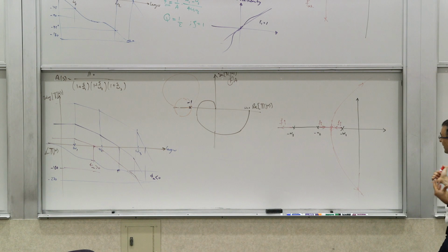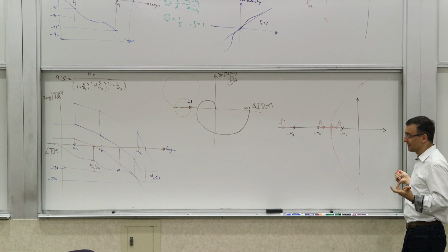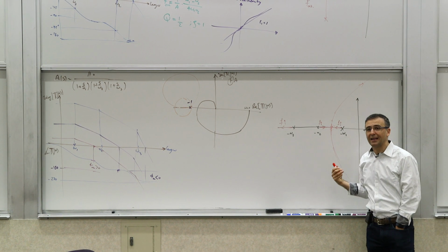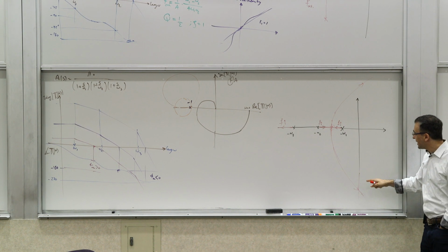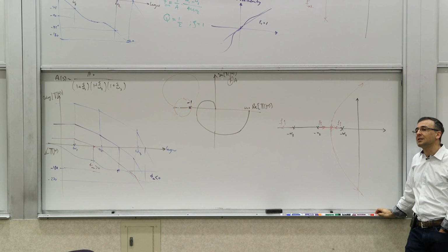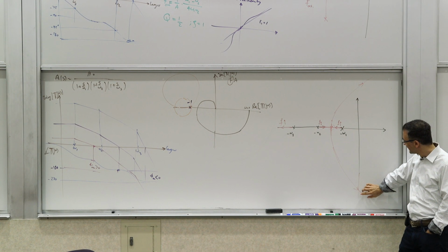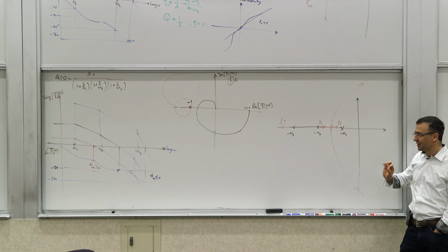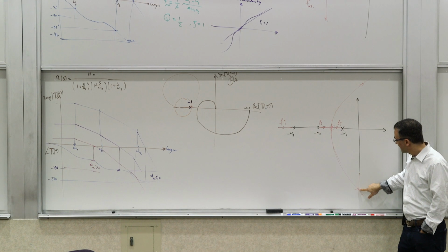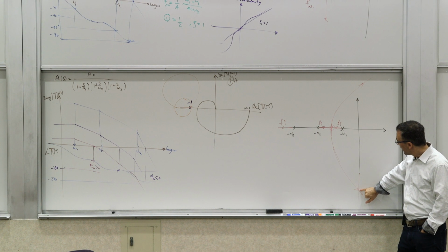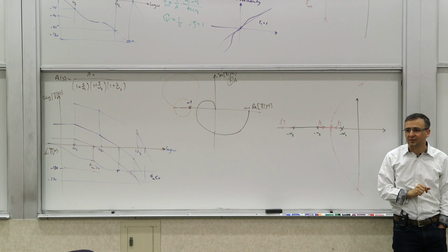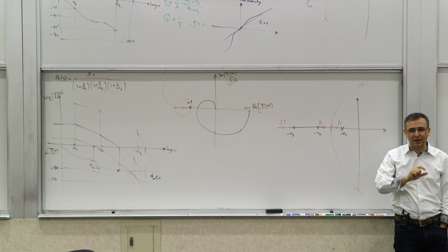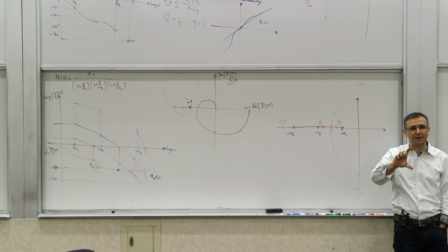Now, if you're making an oscillator instead of an amplifier, one of the ways to think about it is that you're trying to get a reliable pair of poles exactly on the j omega axis, if you're trying to get a constant amplitude, something whose amplitude doesn't change.